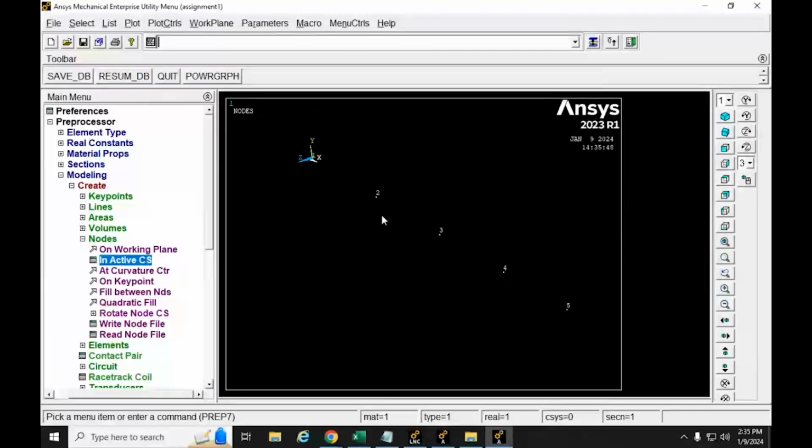So once you've kind of messed with those controls a little bit, if you go on the right hand side here, the first couple of icons here are the predefined views. You can click on those. It'll get you reoriented. To get back to the view that we started off with, it would be the front view, which is the third one down. Click on that, and then go down and click on fit view, which is the magnifying glass with the cube. It should get you back in the view we were at the beginning there.